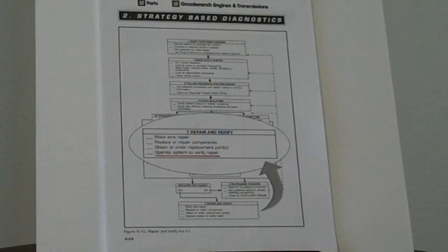Now, according to a 2001 Chevy Malibu service manual, under general information, it states, after isolating the cause, make the repairs and validate for proper operation. Verify that the symptom has been corrected, which may involve road testing the vehicle. An important note here, it is not the responsibility of the customer to verify repairs.